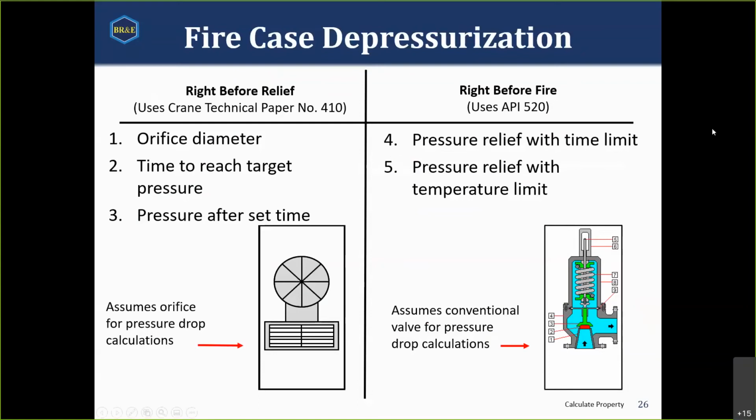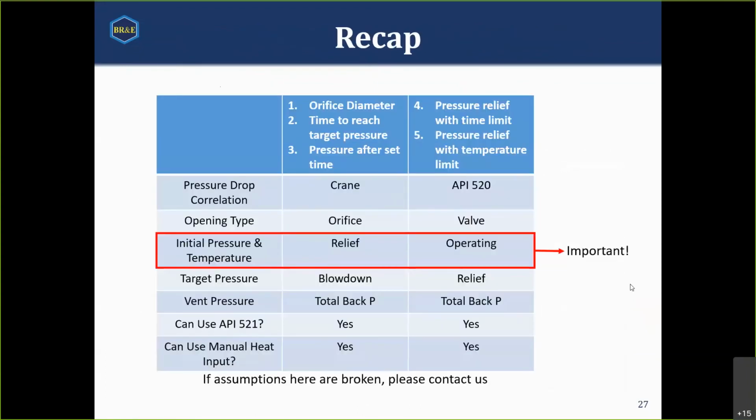You can relieve the pressure over a time period, or you can relieve the pressure with a temperature limit. What sort of conditions do you want to model? Again, it is important, in particular with the rupture disc, that you set your conditions right before the relief. For the conventional valve, it doesn't matter quite as much.